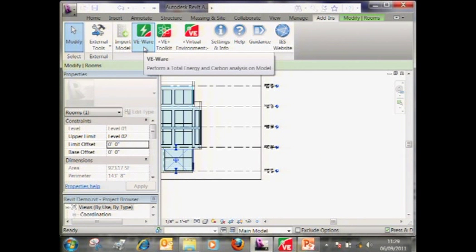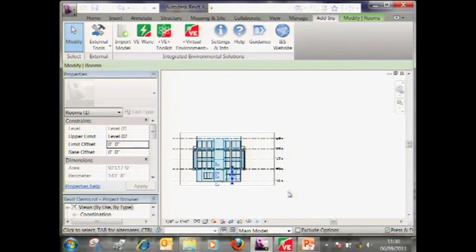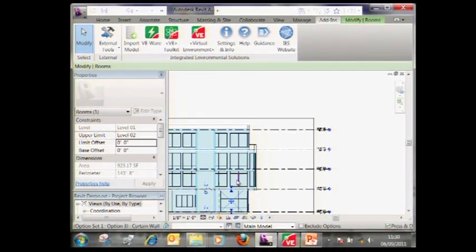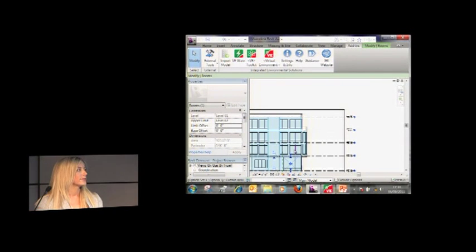And someone asked, is Revit ever going to standardize this? No, they're not, because the reason for having these different is that as engineers, you may treat an entire office or tenant space as one zone, where the architect is going to treat this as a closet, a copier area, a waiting area, a coffee break area, all these different spaces that the engineer may say, I want this to be one volume. I don't want this to be more than one. So you can have as many rooms as you want. You don't have to delete them out, but they will be ignored inside of Revit MEP. So it's all about where you're taking it out of.